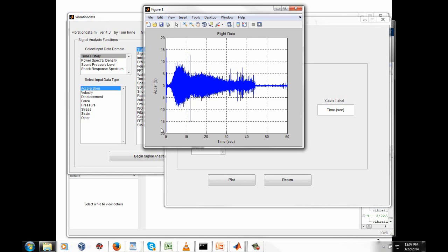And what we have at the beginning is the stage 1 ignition shock, as well as the various launch acoustic effects. And then during the subsonic portion of flight right here, the vibration levels are pretty benign. And then the vibrations build up due to aerodynamic buffeting and turbulent boundary layers and shock waves, attached shock waves, as the vehicle accelerates through the transonic condition and reaches its maximum dynamic pressure or maximum Q condition.